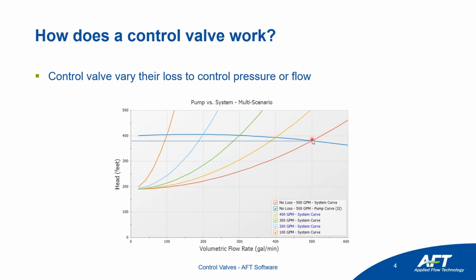And again, this would be kind of our range of controllability. In this example, the pressure losses, if we compare our pump operation, here we were looking at, I believe it's 381 feet of head being added, and here at its peak, it's about 400 feet. So if you imagine a much steeper pump curve, you're going to see obviously a much wider variation in the pressure in your system as well.